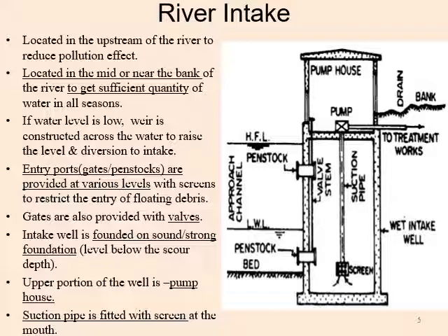The upper portion of the well is known as the pump house, where a pump is fitted and it is connected with the suction pipe through which the water from the intake well will go to the treatment plant. The suction pipe is fitted with a screen at the mouth of the pipe.